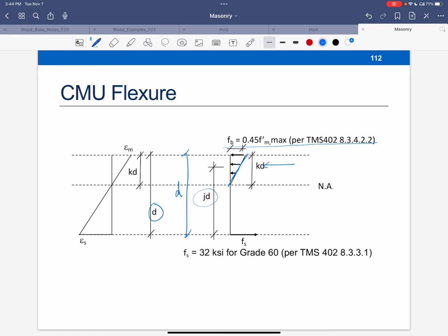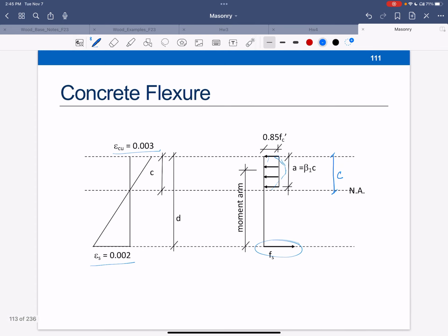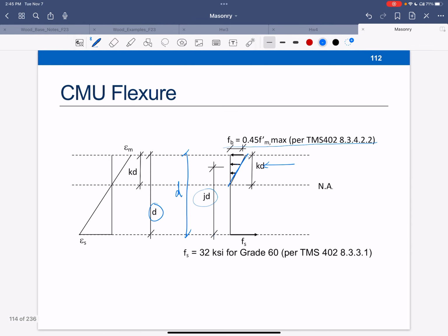A lot of that's left over from looking at allowable stress design. Now, concrete's been LRFD for a long time, but there are some folks who look at the allowable stress piece for masonry and do something similar. So I can do JD for concrete too, but in that case, it would have to be a JD that, same difference, is at ultimate. So anyway, don't worry about that. This is what we're going to do for masonry. So JD is defined that way.